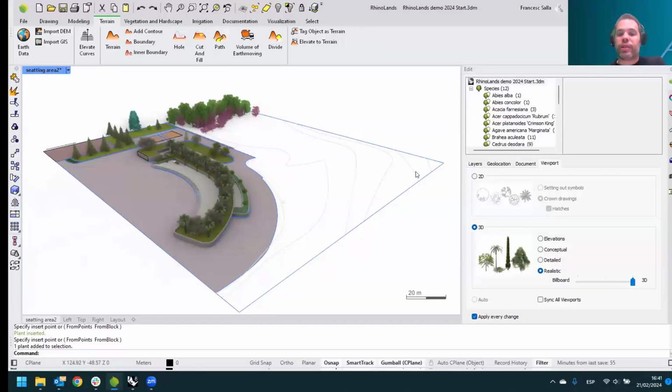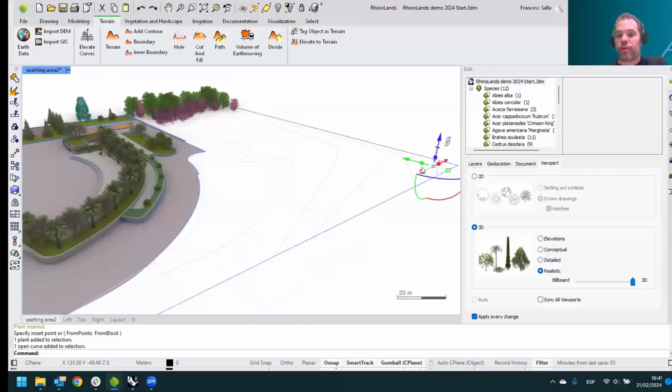But imagine the situation where we have some 2D curves, okay, because you get them from the topography data or from a DWG file, and you get all the contour curves of the terrain on the same elevation. Okay, so the first thing to do when creating terrains from curves or points is to position these curves in the corresponding level or elevation.